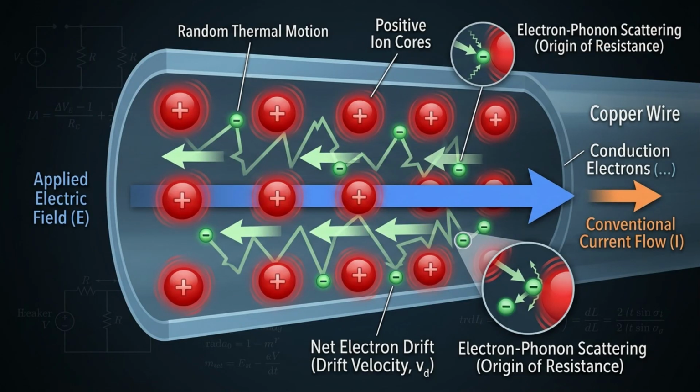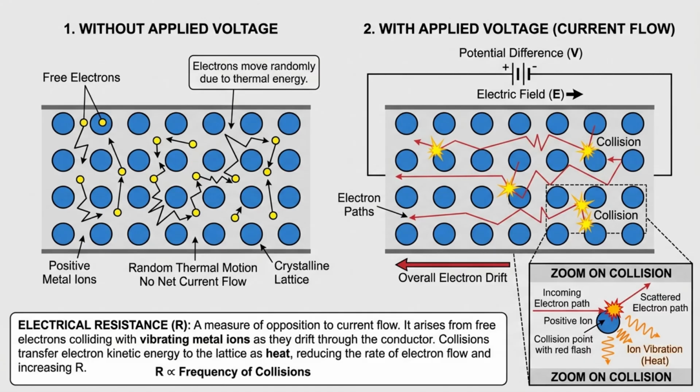To understand why Ohm's law works, consider what happens inside a conductor when voltage is applied. First, a voltage source creates an electric field within the conductor. This field provides energy that encourages free electrons to move. Second, as electrons move through the material, they encounter resistance caused by collisions with atoms and imperfections in the lattice structure. The electric field tries to increase electron motion, while resistance opposes that motion. The balance between these two effects determines the amount of current that flows.